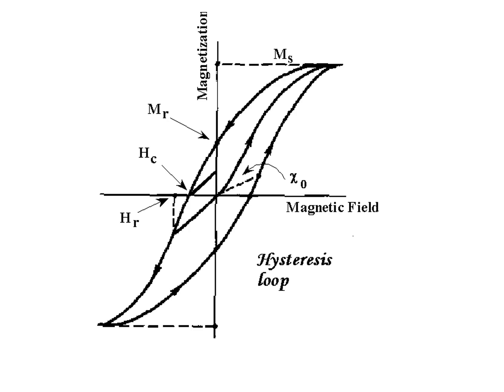When we decrease the field strength, the material will decrease its magnetization, and you can see the curve that is bisecting the y-axis, the first curve with the downward arrow, where the material is going downward. You can see the arrows showing magnetic remanence, and Hc is coercivity.